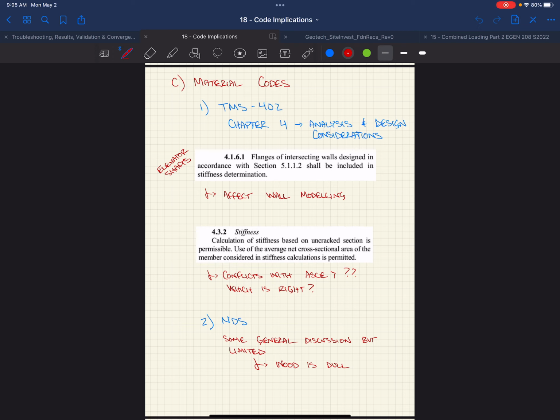I want to talk a little bit about diaphragms and make some notes about dividing them up over collector lines and areas in which you're going to see forces coming and going through a diaphragm. I also want to talk about modal analysis and how you want to simplify the mass distribution so that you can actually run the model. If everything has self-weight, then obviously you're going to have a million different frequencies at which the building is going to vibrate. It might be at 128.3 hertz that you have some beam in some corner of the building that just resonates, and that's not necessarily going to contribute to the overall building behavior. So I was going to make some notes on that.